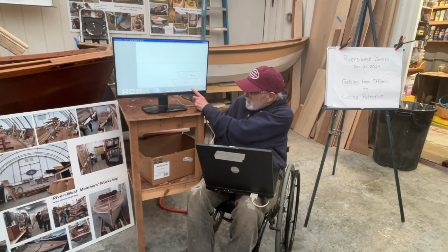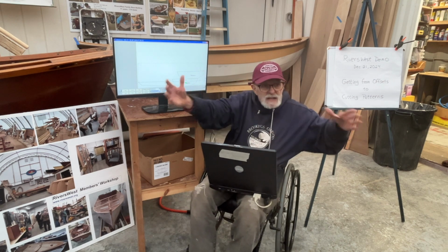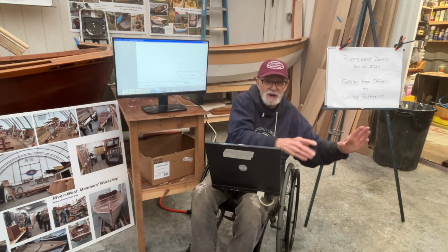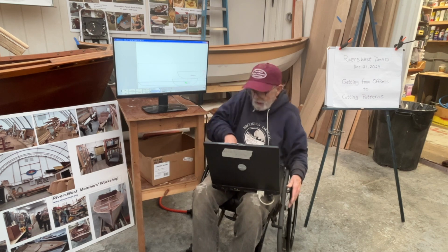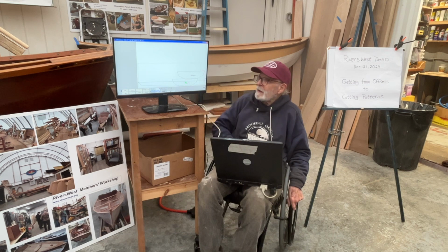This is what your frame is going to look like. Let's pick up a straight, like chine number 3. You can see this is going to be the exact plank shape that you're going to need to lay out on a plywood to build that boat. And so once you've got your numbers, you feed them into the program, it'll do your expansions. So all you did was enter in the offsets? The offsets, yeah.